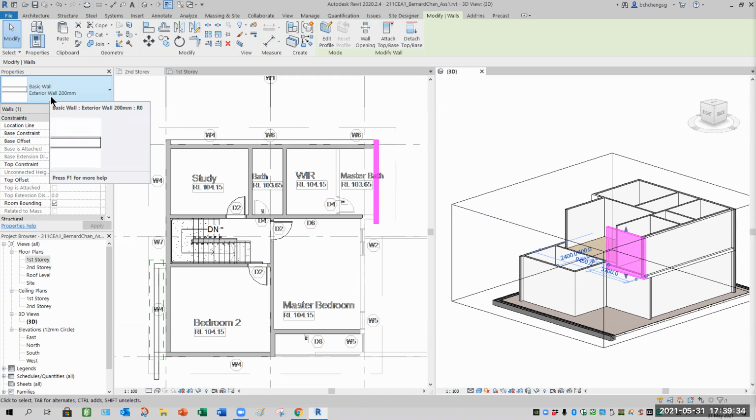That's why we need to name walls differently, interior and exterior, because of the weather, because of exposure to sun and nature. What type of paint is required? Weather bond, right? Weather bond can last like 3 to 5 years, some like 5 to 7 years, depending on things like acid rain. Singapore, luckily we don't have acid rain. Taiwan, we have acid rain. US, sometimes they have acid rain. Chemical, Singapore so far don't have yet, touch wood.